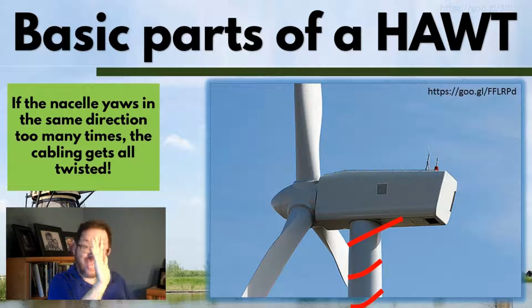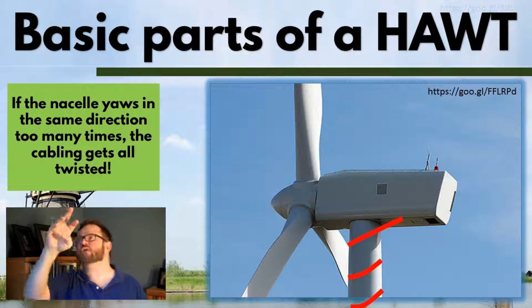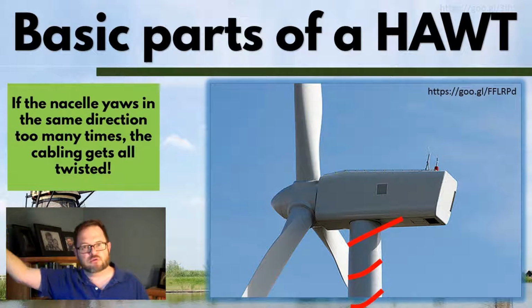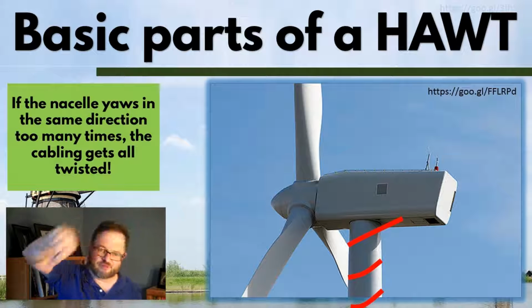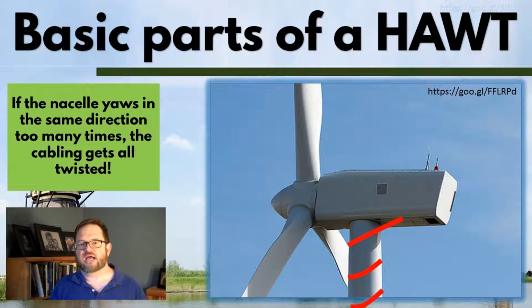So they are attached to the inside of the tower, and then at some point they are not attached anymore. There's some slack, some excess cabling, and then they go up to the generator. Well, as the generator turns, it's getting knots in that it's twisting the cabling. That could be a real problem.